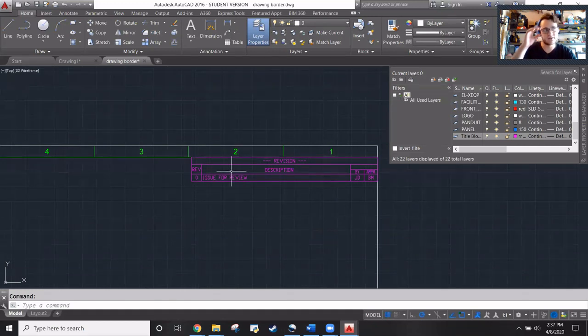So that's another really important thing to keep in mind: generally speaking, you want to try to keep things under macro control in AutoCAD. You don't want to manually set object properties. You want to assign them to a layer that has a set convention for that layer. That way, if you want to change something, you can do it globally rather than manually to each local object.